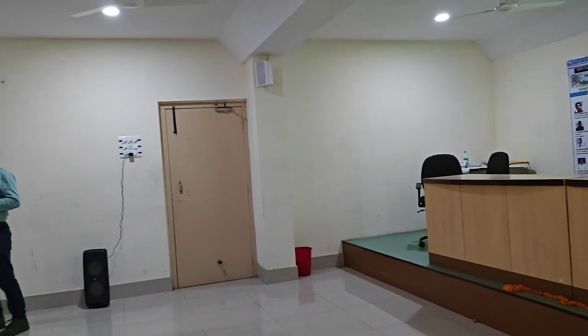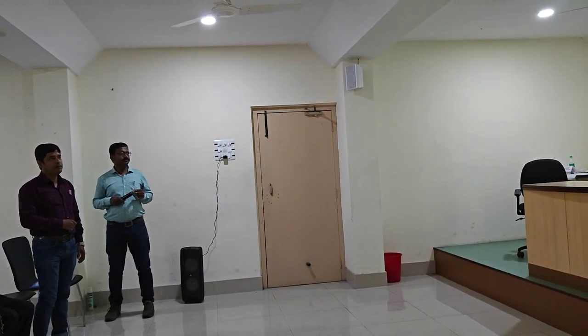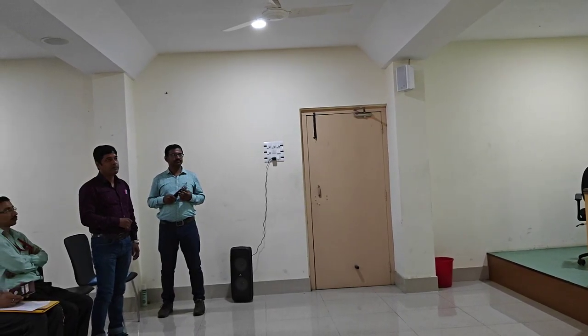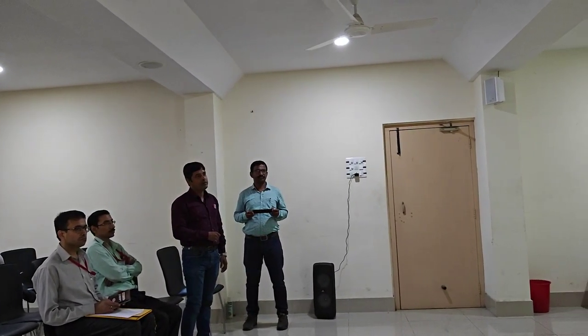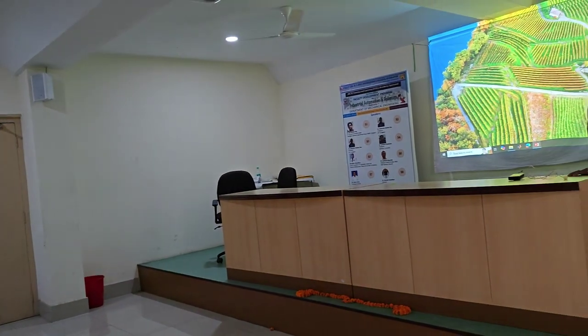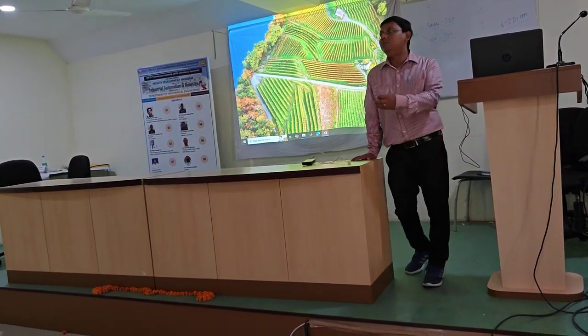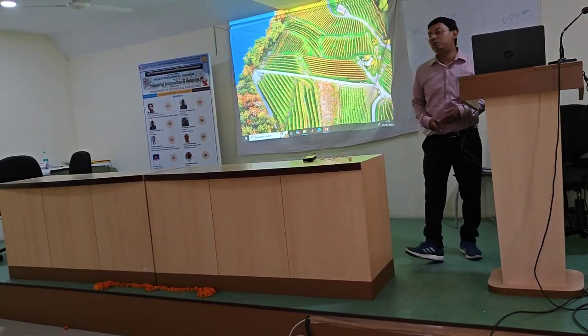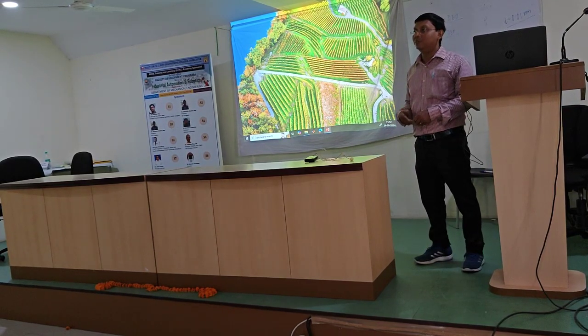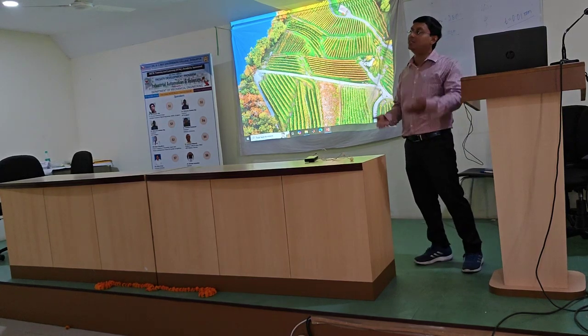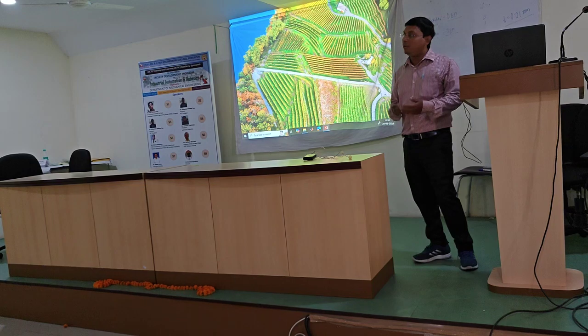And will there be any time gap between the first layer and the second layer, the bottom layer? That is obviously an issue from the research point of view. Depending on multi-material, if you use, a time gap is required. Even with the same material, otherwise there will be no proper metallurgical bonding. In order to give proper metallurgical bonding, you have to maintain that. Those who are working in WAM are working in that particular area. But there is no such standard data book for that, even in the emerging areas. You have to base it on the literature itself. From literature you will get the data. No data book is available till today.